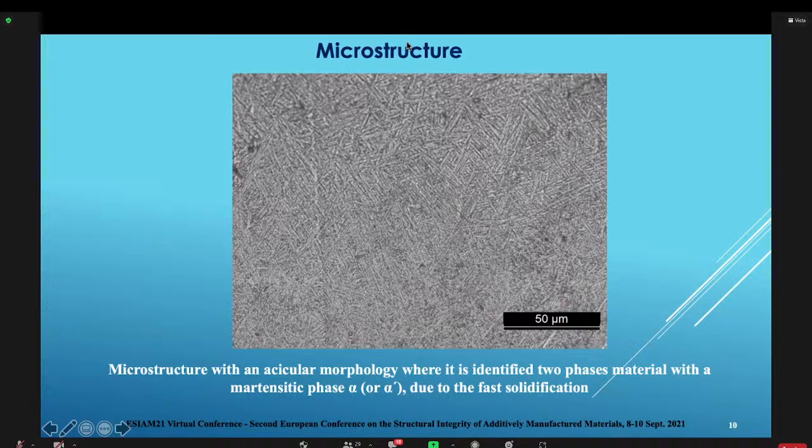Okay, I have a question, if I may. Yes, of course. I'm very interested in the use of DIC and Arcan mixed mode type testing. I'm curious to know if you also considered some form of field fitting to extract the mixed mode fracture parameters or energy integrals around the crack tip.